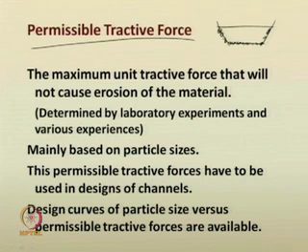We are trying to design erodible channels for uniform flows. Usually these permissible tractive force quantities are determined using laboratory experiments or through various experiences. Senior scientists and senior practitioners of hydraulics have done various experiments and come up with certain quantities for permissible tractive forces.